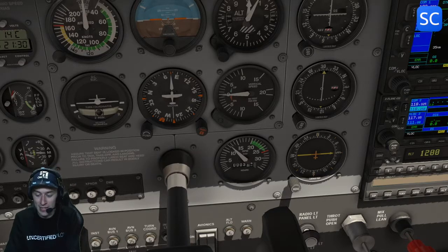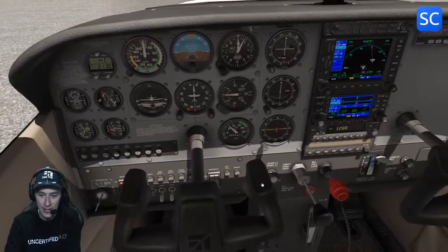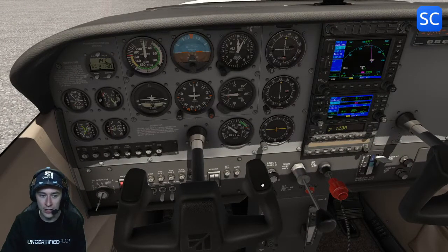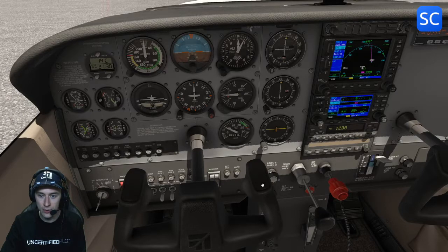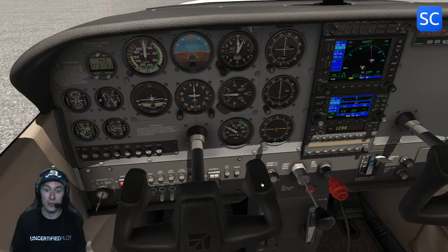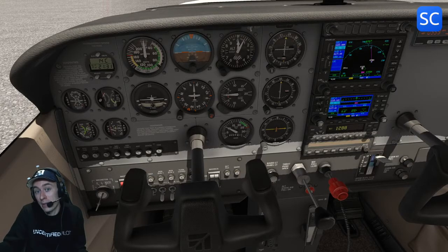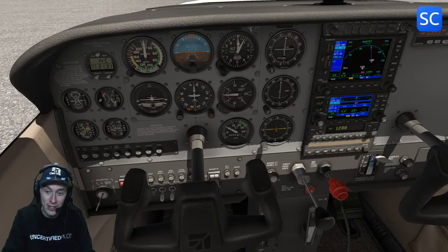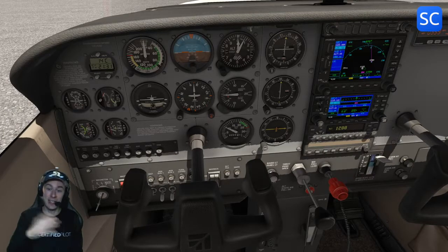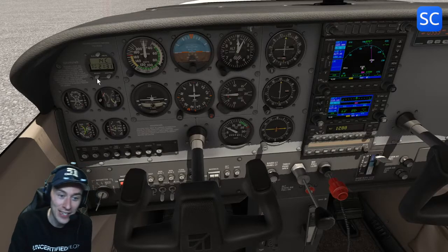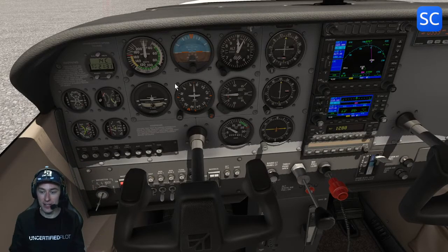It's now simulated. And I do that on 1200 RPM because it's more visible than when I do that on 1000. So once I did, I will go to 1000, not idle, but 1000 to keep the engine warm. If I go idle now, I will also increase the risk of fouling my spark plugs, and that will happen. When we're going to do the run up, you will see that the plugs are fouled. It's just great, I think. EGT is now also nicely high up, so that's in sync.